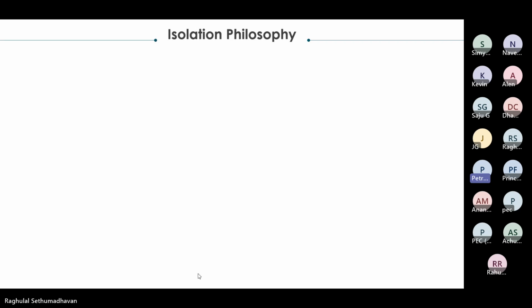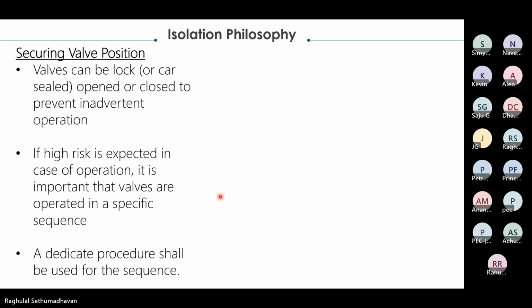Now, there is something else we need to cover, like securing valve positions. You have all seen lock open, lock close valves, right? What are these? For example, there is a pump changeover, or an ESP is to be taken for maintenance. We have seen this. We'll provide lock open, lock close.